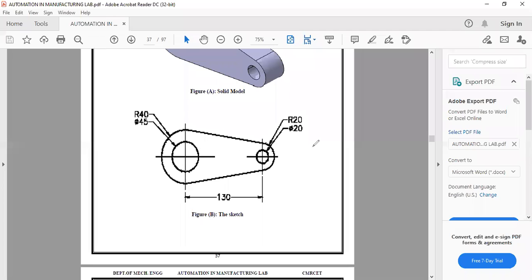For example, you can just draw the upper part or the lower one, whichever is your choice, and then we can mirror this, isn't it? But generally using these circles and all of this, it will be good. So for drawings like this, we'll just draw a complete view. But for those which have more features, we'll go for only a half symmetric view, model only the half part and then mirror it in the sketch itself, and then we can extrude that, or pad it basically in CATIA.